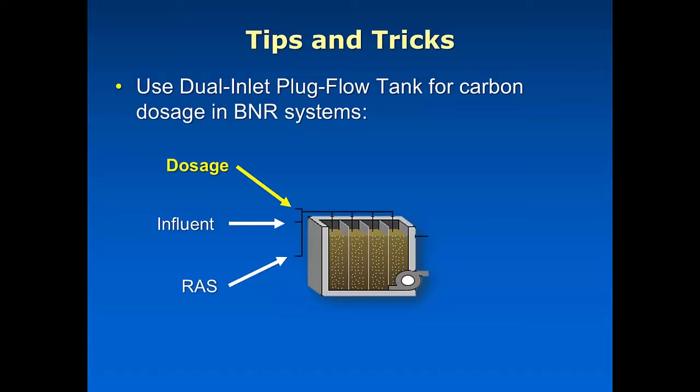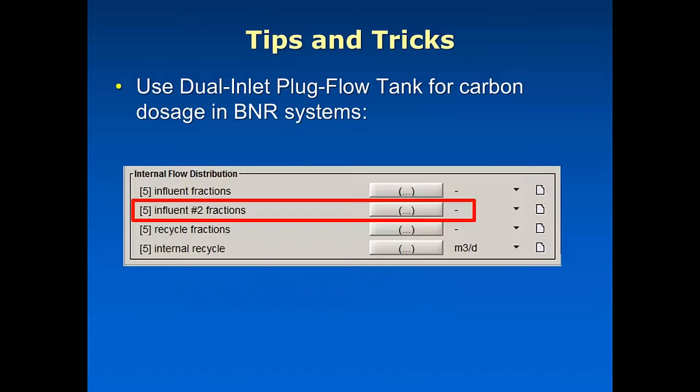And then that extra one is actually specifically designed to be used for dosing things like methanol or acetate. And so those go in there, and you'll note on the operational menu of these plug flow tanks that there is the opportunity to do some step feeding, and that's found at the very bottom of the operational menu.